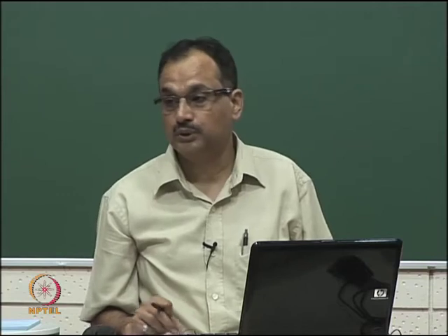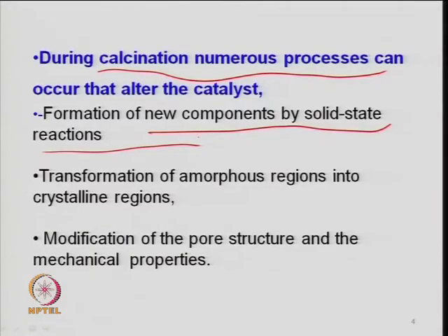And simultaneously, as I said, nickel oxide and aluminum oxide react during the sintering process, and you get a different phase which may be nickel aluminate. That is again important, because sometimes the nickel aluminate may be good. Similarly, in calcium aluminate, I told you 12CaO·7Al2O3 may be a desired phase when you take calcium oxide and aluminum oxide and sinter to a certain temperature and time. So this happens during the formation of a new component. The new phase I am talking about has an entirely different chemical composition, and that may have a different activity in terms of adsorption of a gaseous molecule.